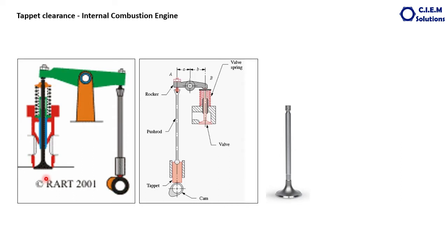And another thing: when the engine is running, all the parts moving inside the engine get heated and their temperature increases. We have provided a cooling system and also the lubrication system to carry away the heat and regulate the engine temperature. The majority of the heat is carried through the cooling system, and some amount of heat is also carried through the lubrication system. That's what we discussed.